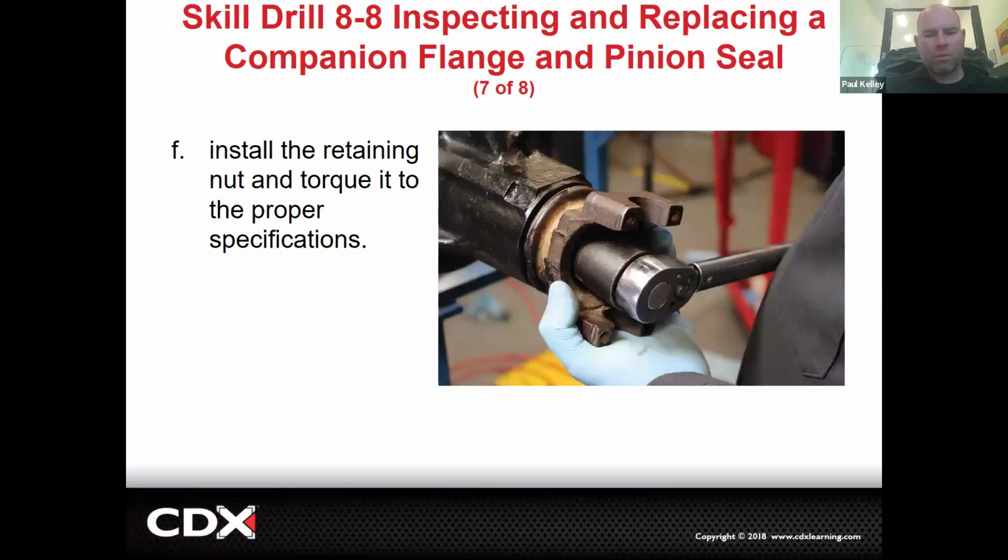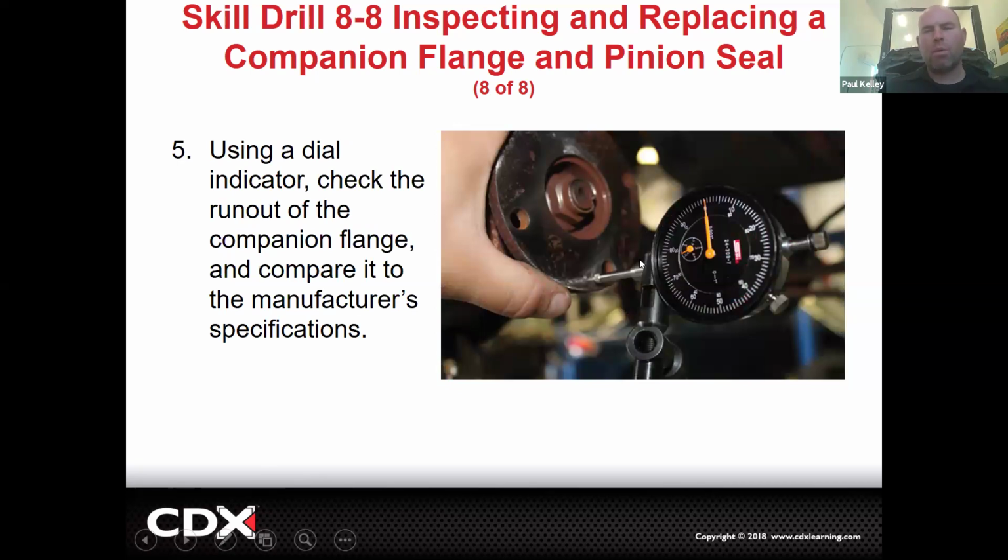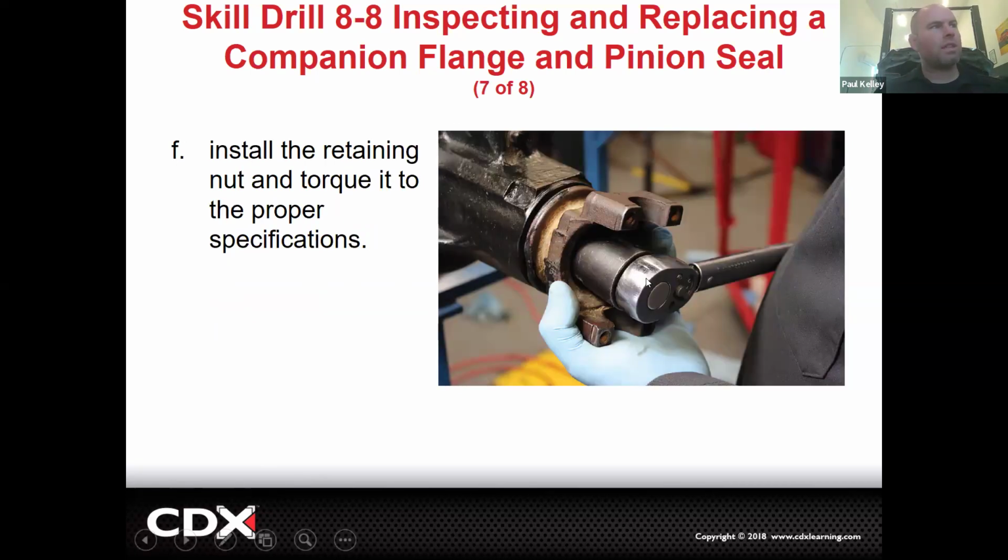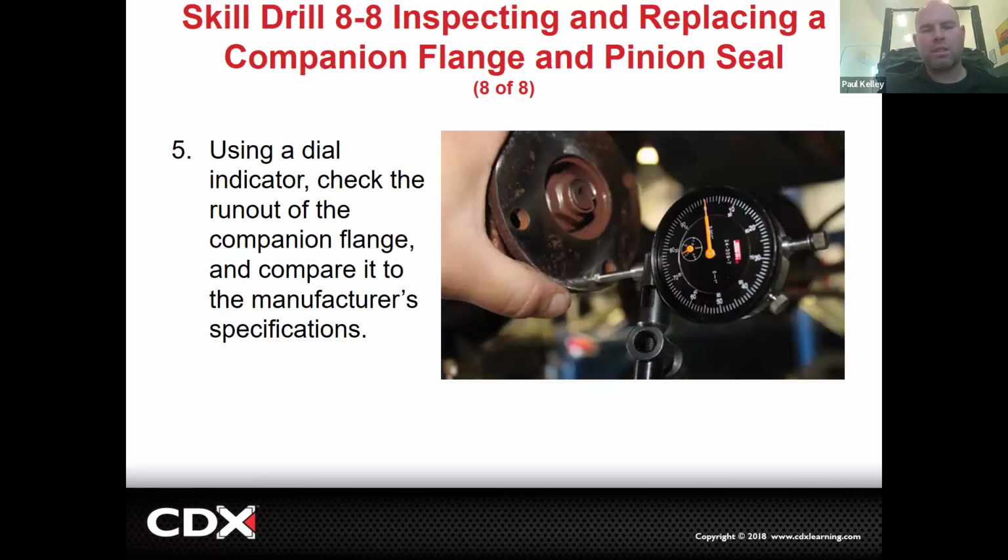According to service information, you can't do this, but in reality, you can torque this nut to spec, but you just have to understand that doesn't account for over crushing the crush sleeve. So I wouldn't do it like that. I would make the mark and do the mark. Okay. But when you do tighten this up, it has to at least meet the minimum torque spec, but a lot of times you'll meet the minimum torque spec, and then to set the preload, we're actually over torquing because it's crushing. It's kind of a weird thing. When you see the steps for doing a diff, it'll make sense.